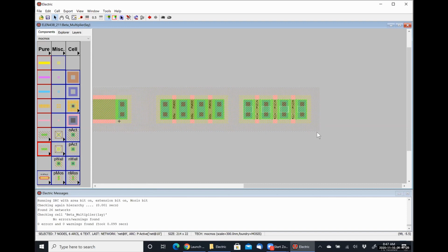I still need to be able to connect my, I'm trying to think about the connections and all that kind of stuff that I'm going to have here, because I'm going to have a connection to VDD up at the top. I'm going to have to tie these gates together. For my really, really large one, I need room to run that gate drain connection down. That should be pretty easy.